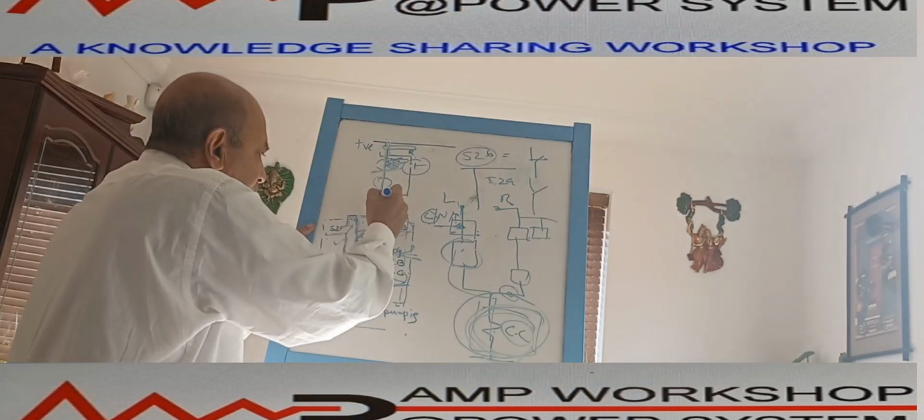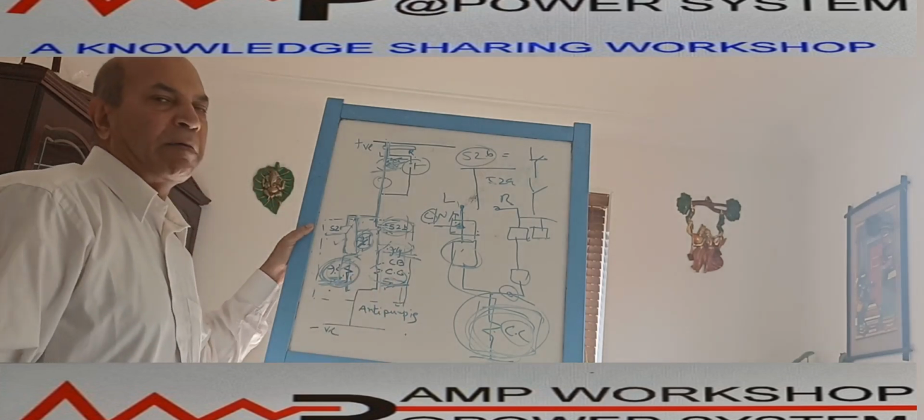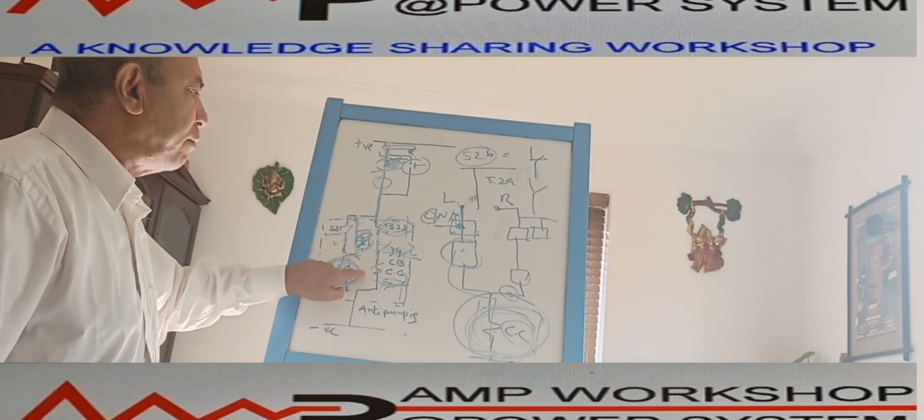The breaker is closed and then it opens on fault, but this anti-pumping relay remains energized, which is causing this contact to stay open. So the closing coil will not get any power. Though the breaker is open, it will not get any signal, so the breaker will not close.